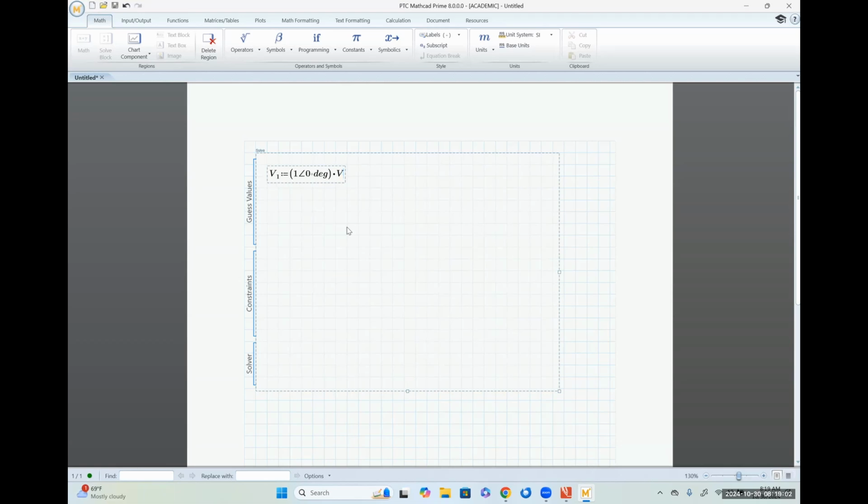So here, when we're manipulating complex numbers, it is going to be critically important for us to explicitly multiply and not let MathCAD really have any opportunity to confuse what we're trying to do, or things are going to go horribly awry very, very quickly. So anytime I'm assigning a unit or anything like that, I'm going to explicitly multiply. I'm going to be very judicious about how I apply my parentheses and all that kind of stuff, because it's so easy to get errors in our system.